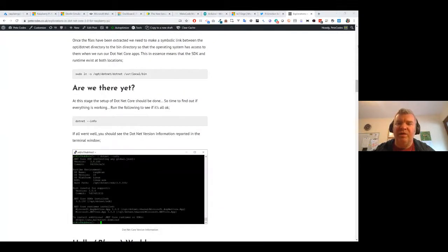And I've got some C# code here, which is hacky, just to make stuff work. But you can see there's nothing particularly fancy about it. There's the same connection string that I had there before. And then we create something called a device client. And I've got a message counter that I'm doing something with as well. We instantiate that device client with a connection string and then create a Gpio controller.